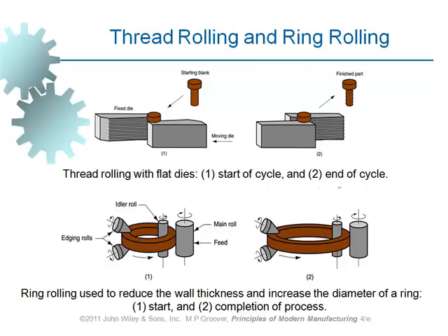By the way, the quality of the material that you get when it is produced by thread rolling is greater. The reason is that the surface produced in this method is a material which is squeezed, and it is stronger and harder than a material which is cut by a machine tool. And also, there is no waste of material. Any material which goes in, the same volume of the material comes out. There is change of shape only, without any removal of the material. So we get a better set of properties, and also, as I said, the rate of production is really greater than machining.